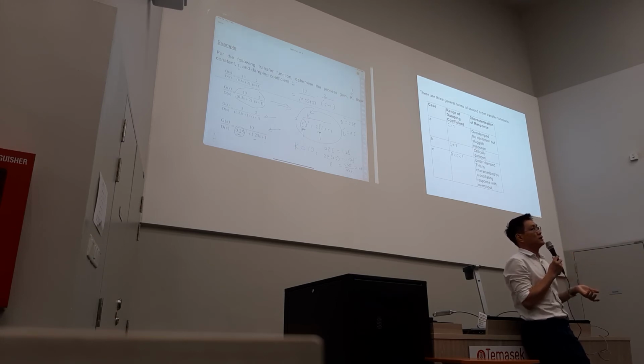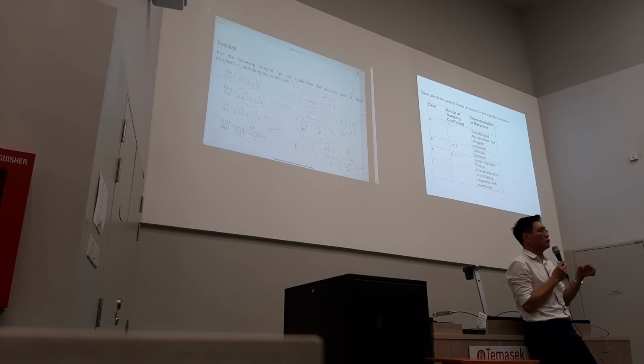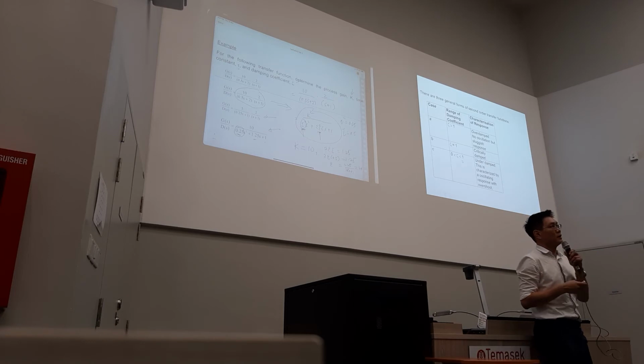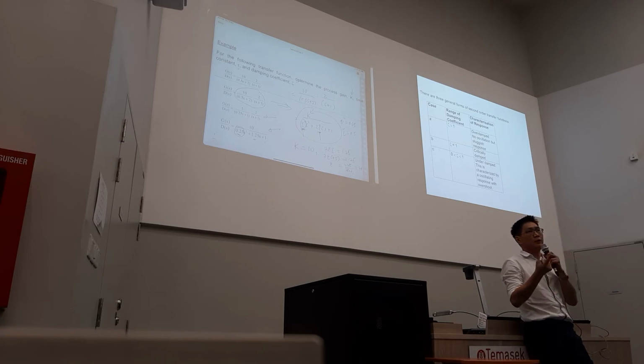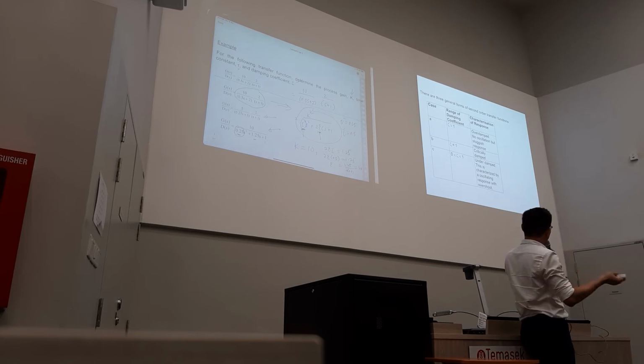So I may need to invest more or buy a system with better instruments, and then my set point and all this for the controller has to be very accurate. And then the last case, which is the C, the damping coefficient is between 0 and 1. Between 0 and 1 means what? Like 0.1, 0.2, 0.3, all the way up to 0.9, or maybe 0.55, or things like that. Cases like this, we call it underdamped, whose characteristic is an oscillating response with overshoot.